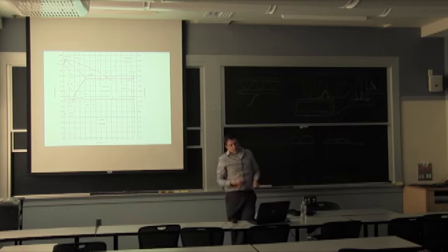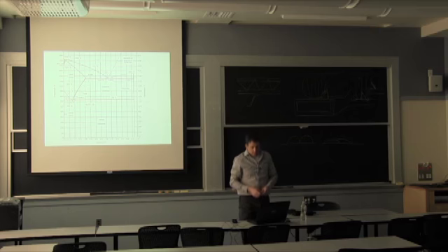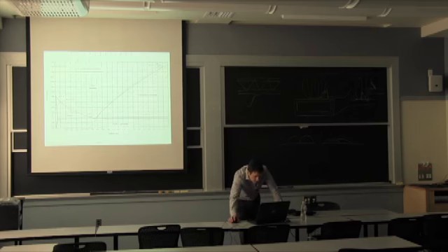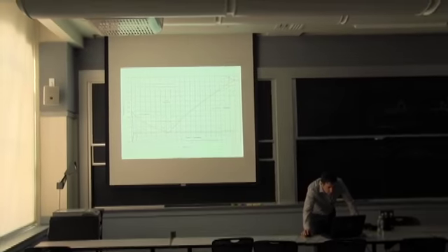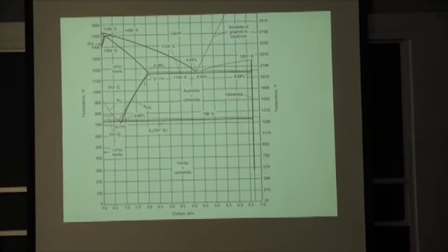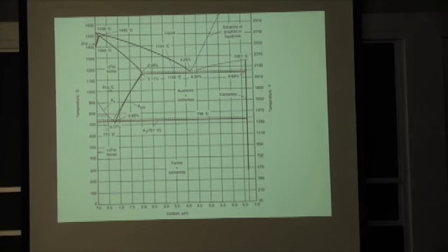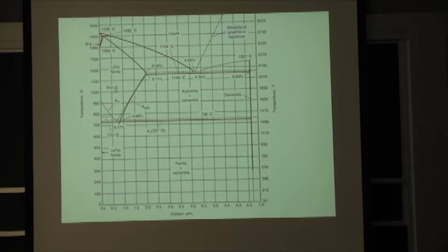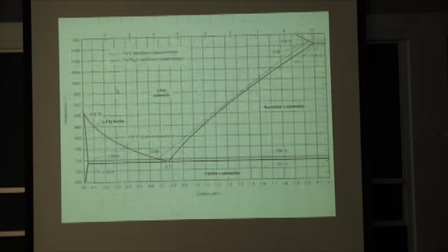If you cool down the steel slowly, there's a limit to it. There's a solubility limit, and that shows up in this diagram. So as long as you put in beyond 0.02%, you'll form some cementite when you're cooling to low temperature. So what I'm doing here is blowing up the left side of that phase diagram to look at this one. This is the most relevant for steel.